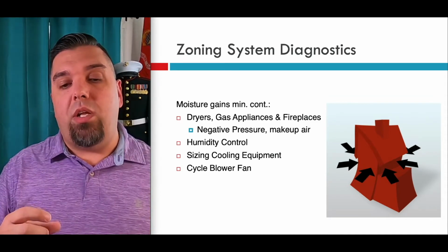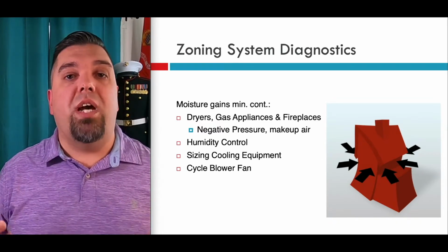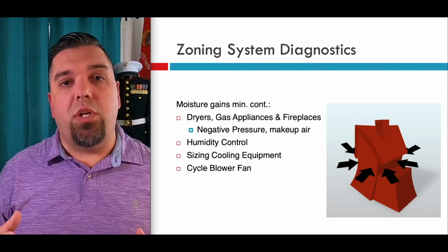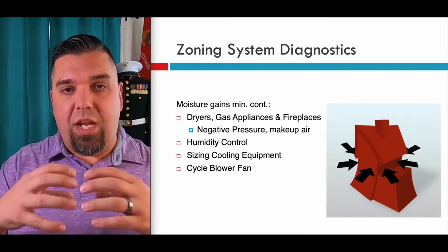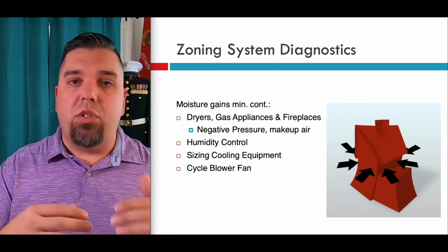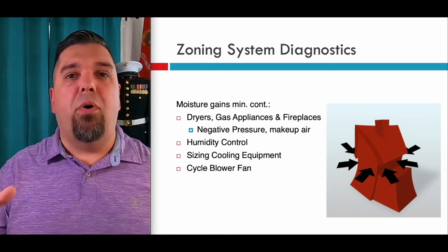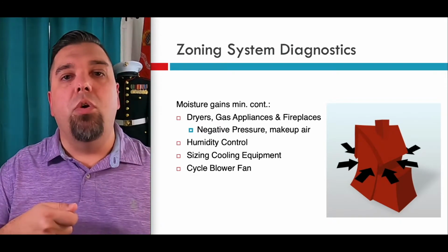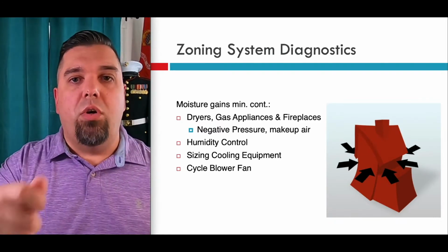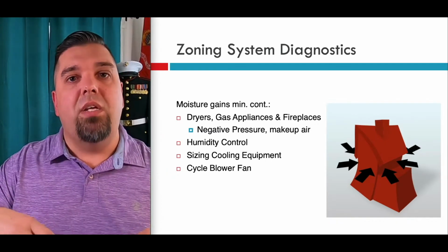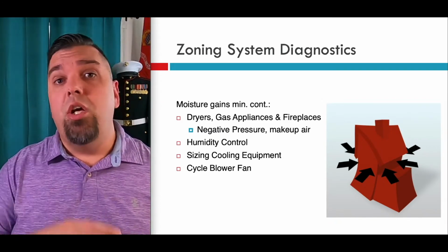Now, what's really important is if we have a negative pressure in a space. As an example, on the second floor of a Cape style or colonial style home, I see a lot of central returns in hallways. If we take all of the air for a 2 or 3 ton system from the center hallway, and we just rely on undercut doors to pull air back from all of the bedrooms, it is very easy to pull a negative pressure in the hallway if anybody closes any of those doors, because we're supplying all the supply air to those rooms. When a door closes, we are now going to pull more air back from that space than what's connected to it. Now that air has to come from somewhere, and it could come from the fireplace, the kitchen, anywhere, right?